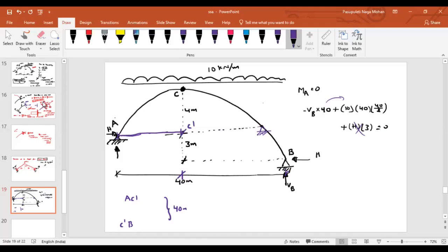Now, what is the equation that we know? Let us assume that this unit is a parabolic arch. I know one thing, what will be my relation? I know that y will be equal to 4h by L square into x into (L minus x). All right. How can I find it out somehow? By using this equation, just think about it. Can I find out this length?